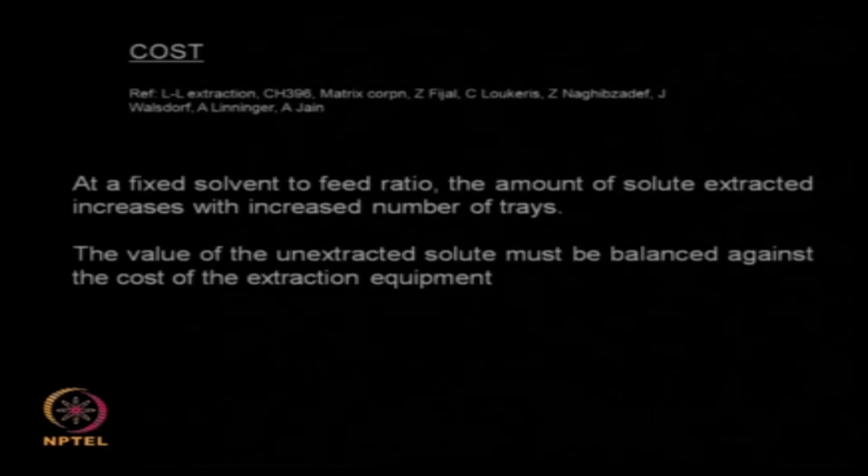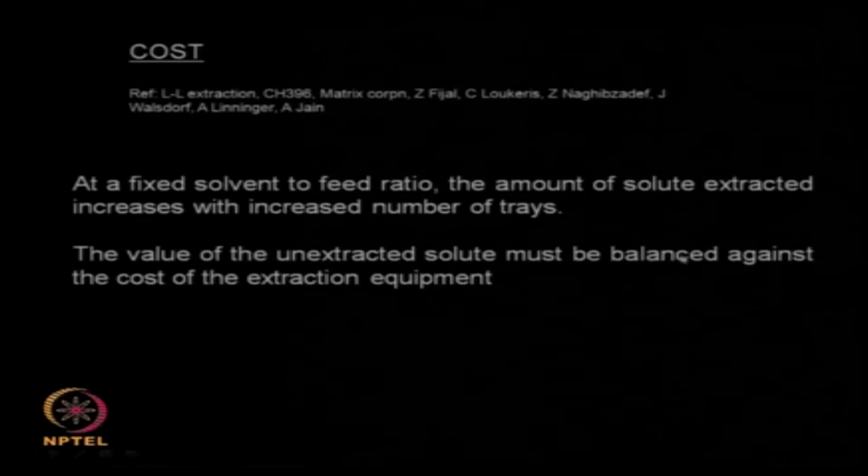If I have many stages, I will be able to increase the amount of solute that is extracted. The value of the unextracted solute must be balanced against the cost of the extraction equipment, because if I put many stages, I am going to increase the cost of the overall liquid extraction process.